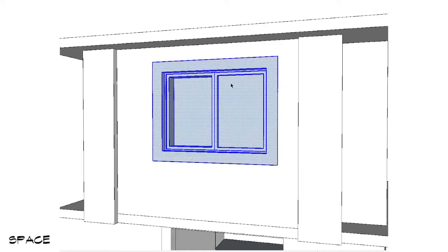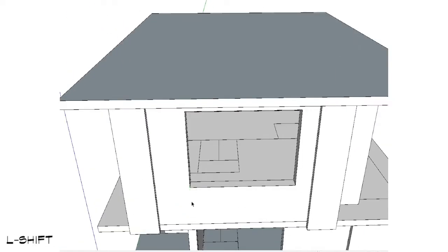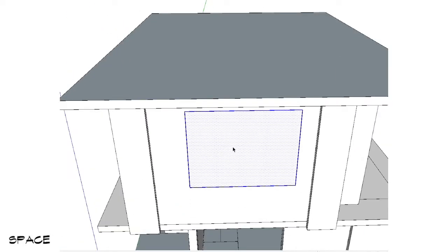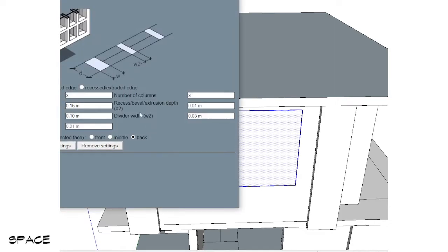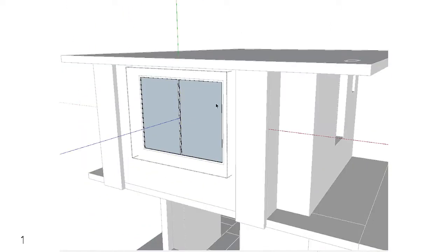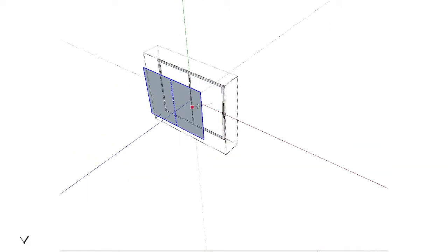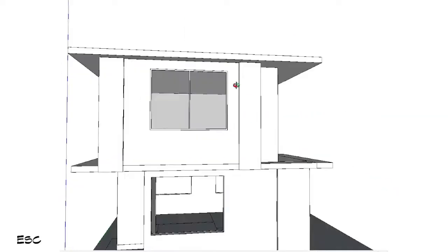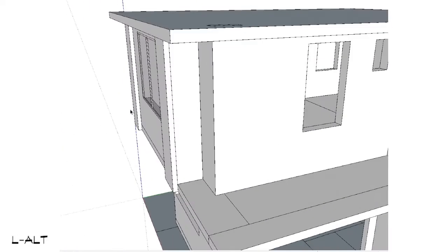and doing that. However, if you have the 1001 bit tool, you could just use the panel divider, put the frame dimensions and the number of columns. There, that's it. Because our glass is already grouped as one, so we could just put the glass material to have the transparency.